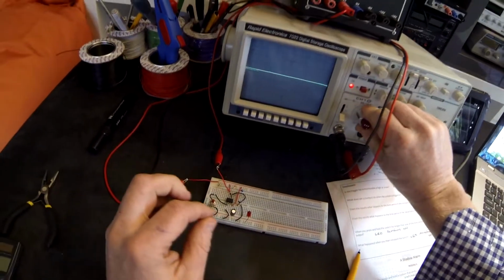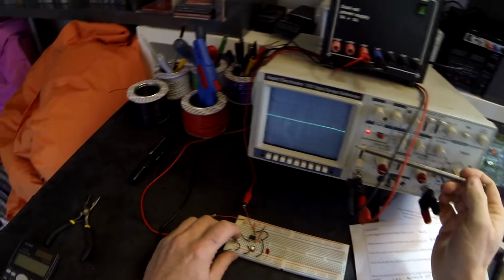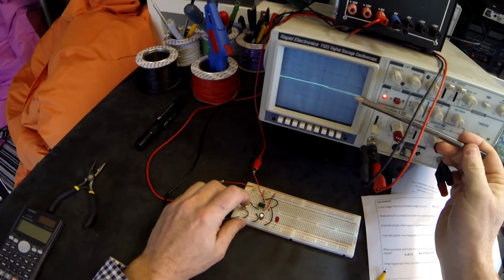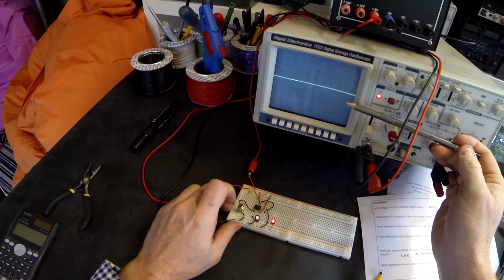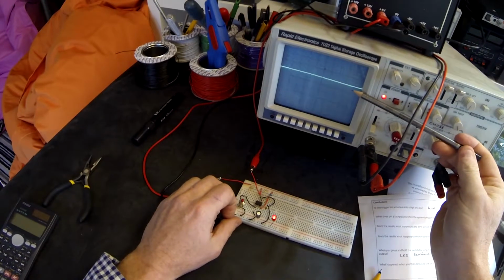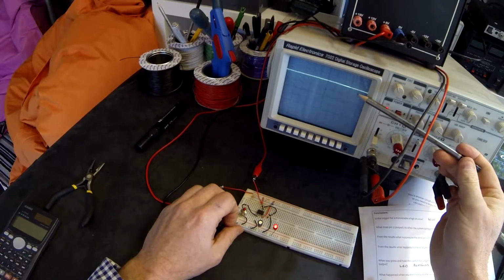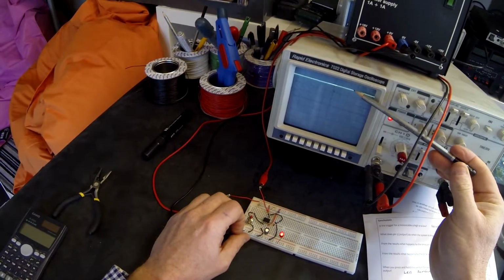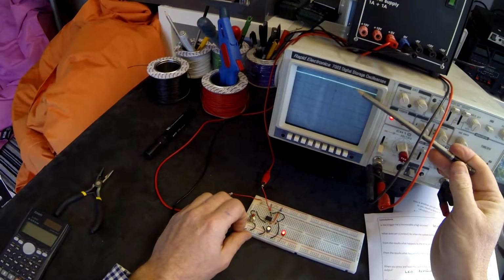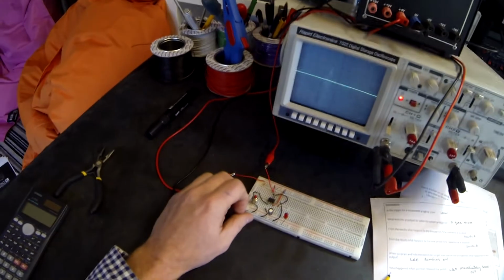Just going to change my value there, and I'm going to start my circuit. And you'll see something interesting here, because you will see the capacitor start to charge. So I press it, the LED comes on, and here we go, our capacitor is starting to charge. And it's got to 1 volt, 2 volts, 3 volts, 3.2, 3.4, there we go. It got to about 3.4 there.